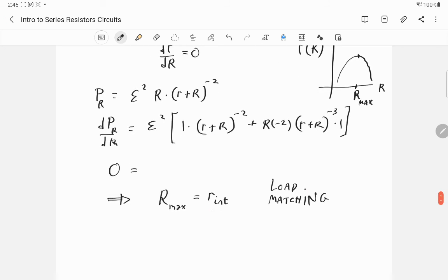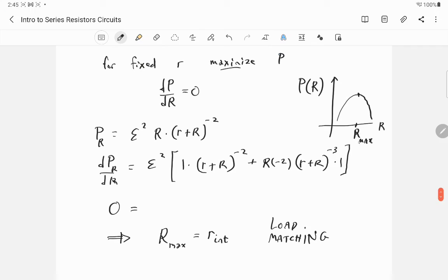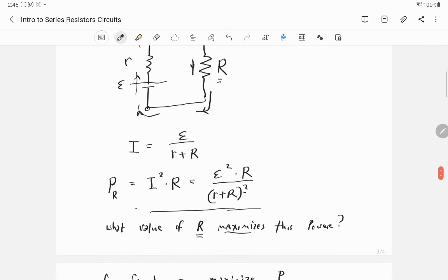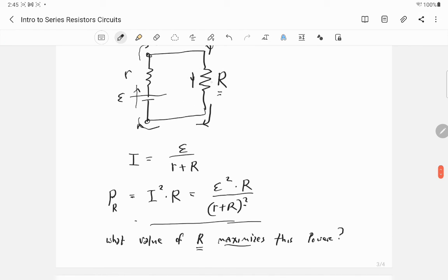It's like the sweet spot of having a resistance that is not so big that you squeeze off the current, right? You don't want capital R in our circuit to be so big that the current is too small. If the current is too small, then the power is 0, right? But if R equals 0, then you get sort of the opposite thing to happen.